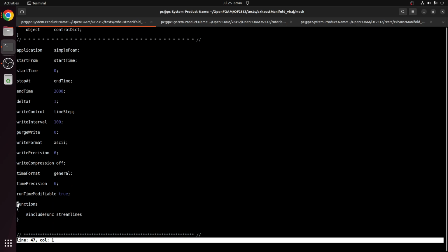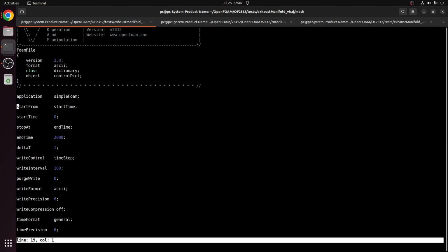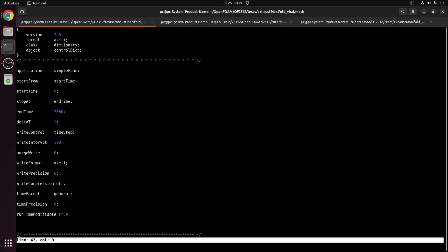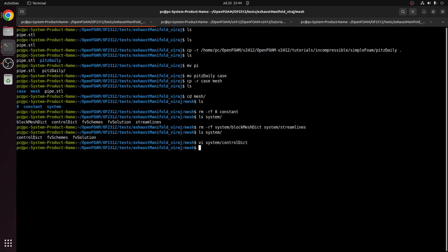These functions are also not needed. A very simple controlDict is needed. The controlDict just says that it is an OpenFOAM directory; it is not of much use at all. So a very bare minimum controlDict is required, which is more or less sufficient to do the meshing part. Now the geometry will always go into a folder called constant/triSurface.